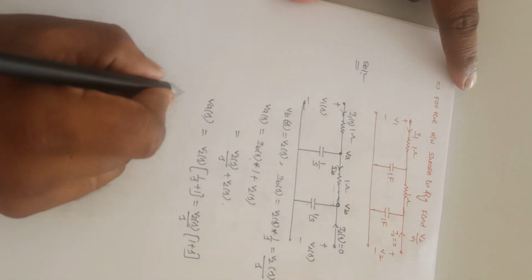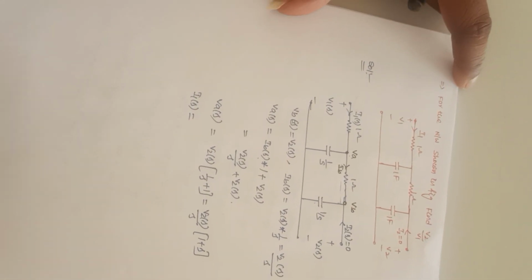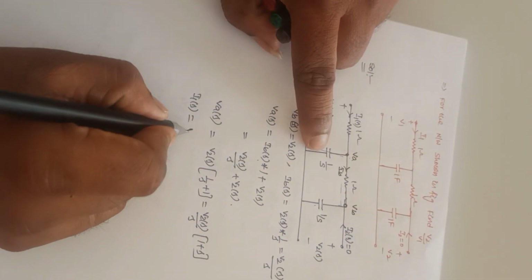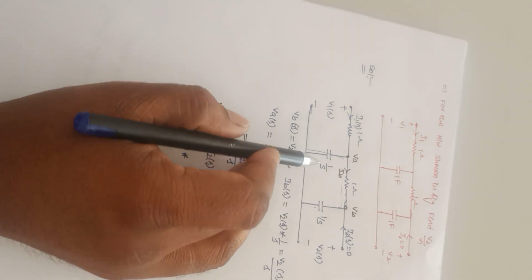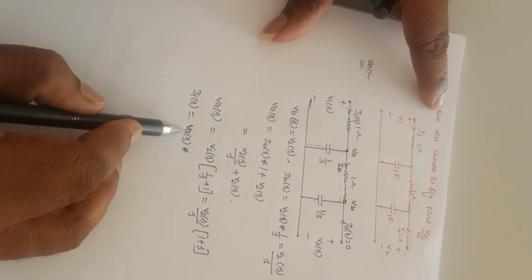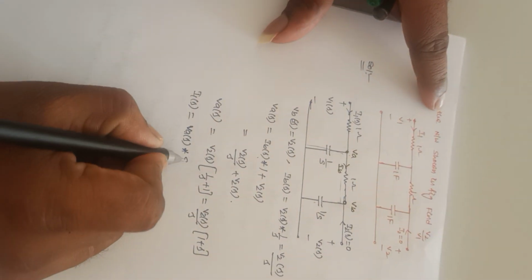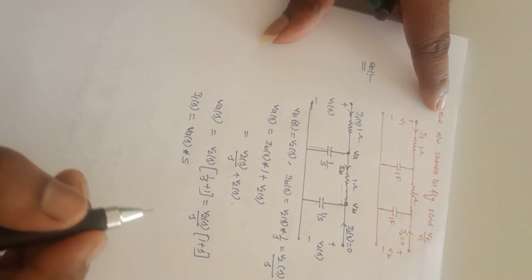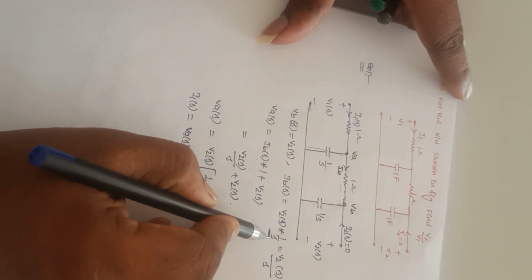Now I1 of S is equal to, for this, this current is equal to this current plus this current. So this current is VA of S into, actually it is an impedance. The impedance of this one is 1 by S. I need to multiply with admittance. So the admittance value is 1 by S, that is S here. VA of S into S. So this is an admittance, S value. Also, I forgot to write here, this one is also an admittance.